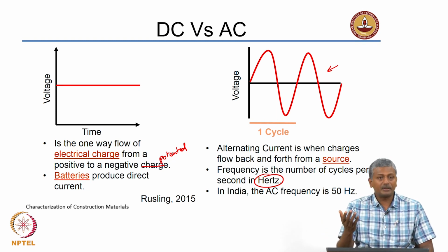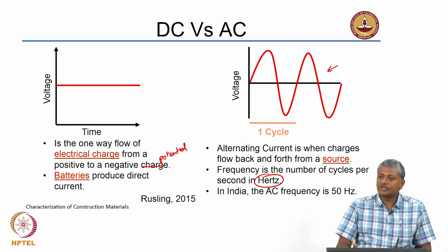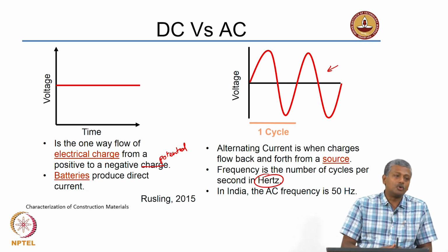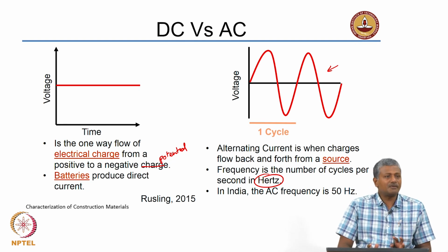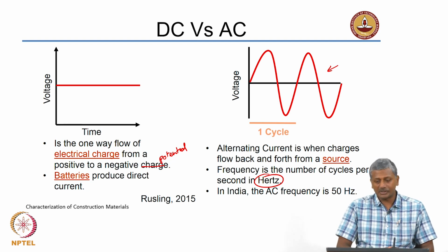So, what is common as far as India is concerned with respect to your household electricity? How much voltage is typically given? 220 to 240 volts, right, and frequency of 50 to 60 hertz. If you go to the US, for instance, they may have a different frequency, they may have a different voltage. 110 volt system is typically followed in the US and in Japan, for instance. The frequency generally varies between 50 and 60 in most countries. Okay, in India mostly it is close to 50.